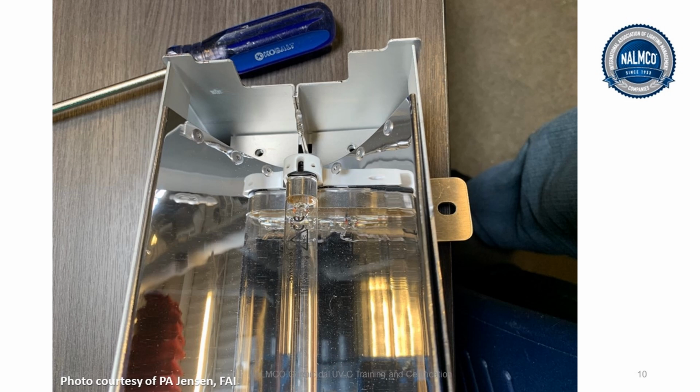So I talked about taking a look at fixtures to make sure they're assembled correctly. Is the reflector actually fixed in its proper place? Are the lamp ends actually properly located in the lamp holder, in this case a twin pin? Was the lamp actually rotated, or is it just sitting in that slot and not firing or putting out UVC?